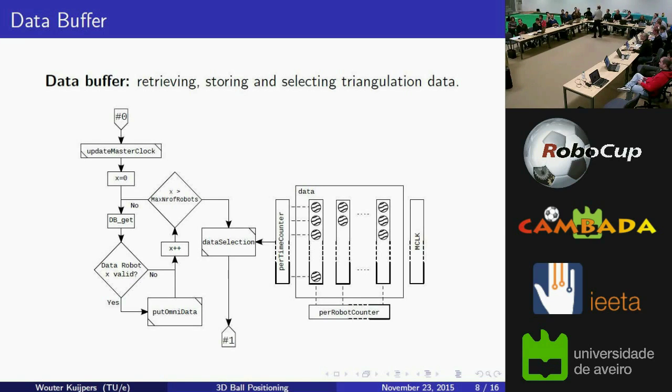Of course, yeah, so in this case, it's anyway quantized. If I would get more precision, that would in the end give a better accuracy of the triangulation, that's for sure. But in this case, this algorithm doesn't do anything different. This could be used in decreasing the value of the measurement error covariance, the R I presented. This could be lower if we make sure that, for example, the communication timestamps are really accurate.